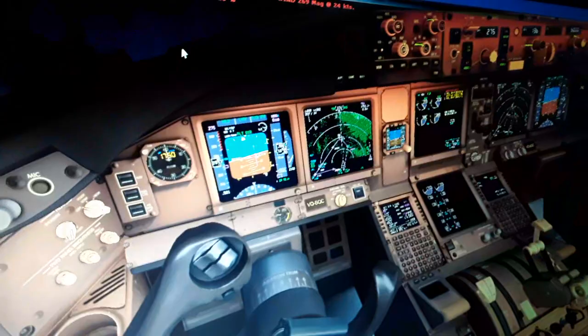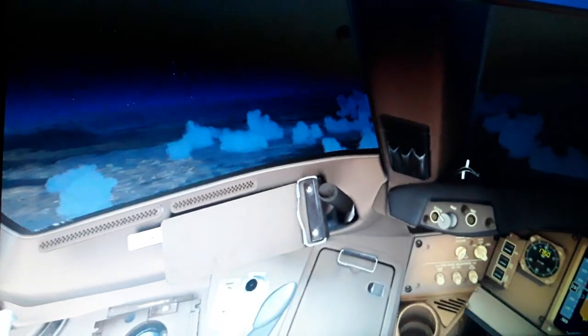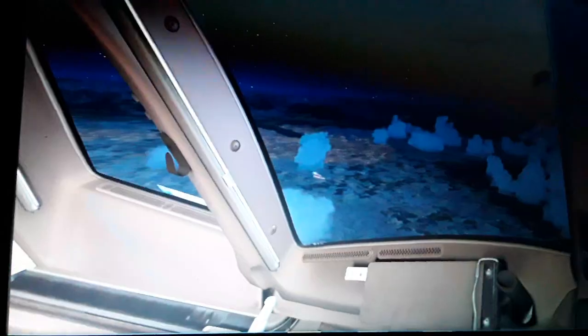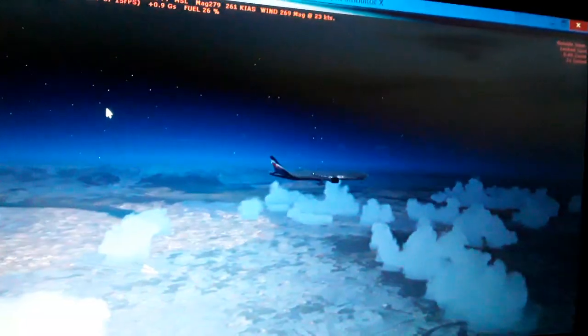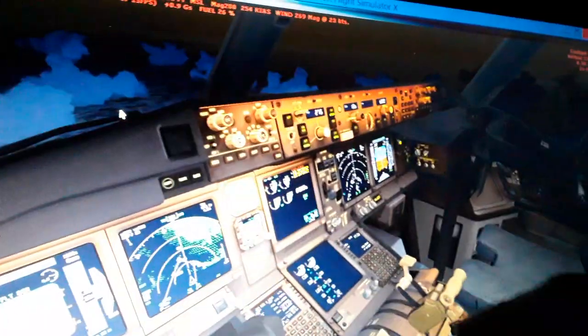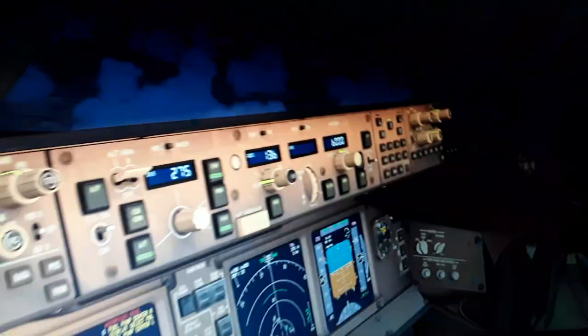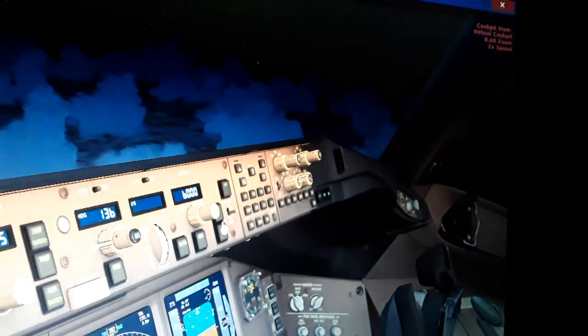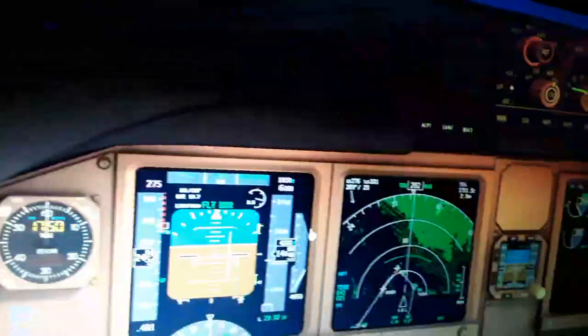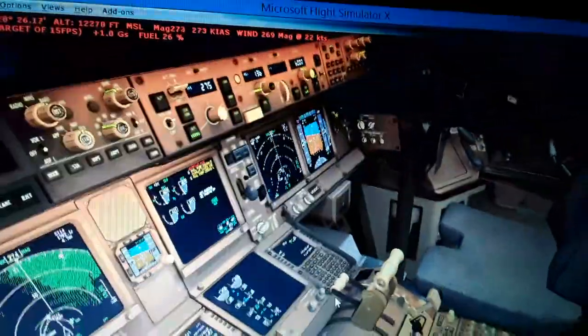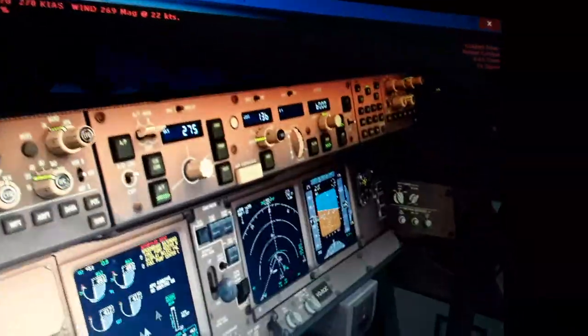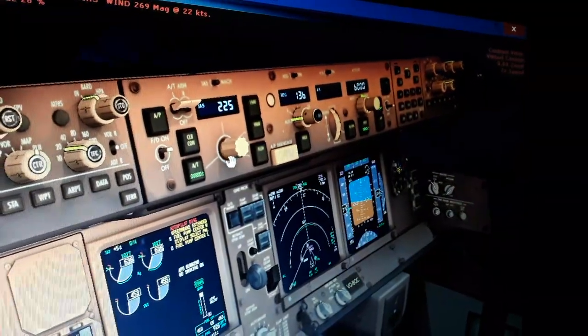Extend the landing gear to slow down a little bit. We're gonna use a shortcut for landing. Actually, we keep flying with about 900. No, and now we slow down. We need to slow down. We fly with 500 kilometers an hour, so we're gonna use also the LSZH localizer for this approach. So I'm gonna have also some flaps here, and also decrease the airspeed here to the approach landing airspeed.